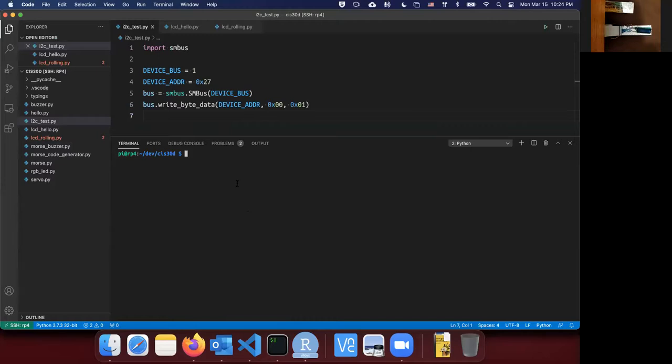When we write the address in the program, we use hexadecimal notation, but the standard I2C uses 7 bits. So basically you can have up to 128 devices, and that's kind of the advantage of I2C. You can connect a lot of them to your system, if you want to.